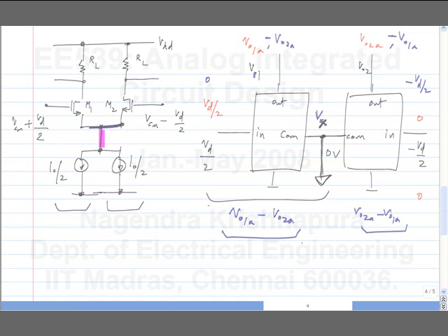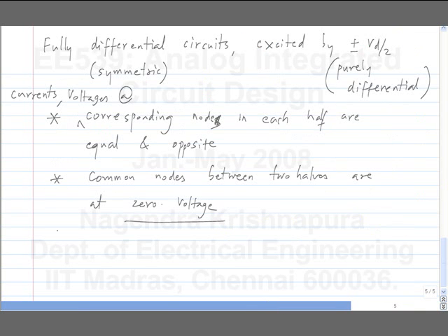Okay. We want to get the individual voltages, that is fine, because we analyze one half of the circuit and we know that on the other half we will get the same magnitude and opposite phase. Okay. So this concept, the circuit that you get by grounding the common node, is known as the differential half circuit. So this will let you analyze a simpler circuit, right? Basically you analyze half of the circuit.